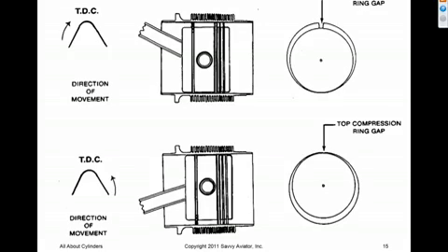So the leakage reading that we get on the meters might be pretty mediocre in the case of that top drawing, or might be just wonderful in case of the bottom drawing. But the differences have nothing to do with cylinder condition. They have to do with just where the piston has settled inside the cylinder, and just where the ring gaps happen to be at the moment of the test. And since compression rings migrate randomly during operation, we can never predict where they're gonna be when we do the compression test. One of the things that this particular drawing was trying to illustrate in the Continental Service Bulletin was that if you bring the piston to top dead center in the normal direction of rotation, check the compression, and you don't like what you see, try to bring it to top dead center in the opposite direction of rotation, and you may very well get a much better reading. And whatever the best reading you get is the one you want to write down.